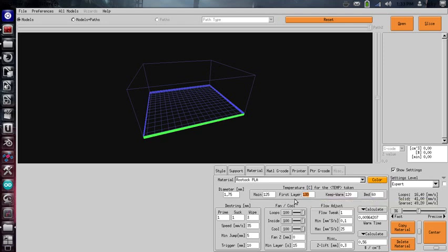I will tell you that turning these to a lower value will increase your overhang abilities, but it would also be harder on your extruder. Setting it too low will mean that you will end up having problems because your material is not fluid enough. Setting it too high will make your overhangs terrible, so it's good to sort of experiment with values here. Keep warm, not something you're going to need to worry about. Basically set it to somewhere just slightly below your main temperature.